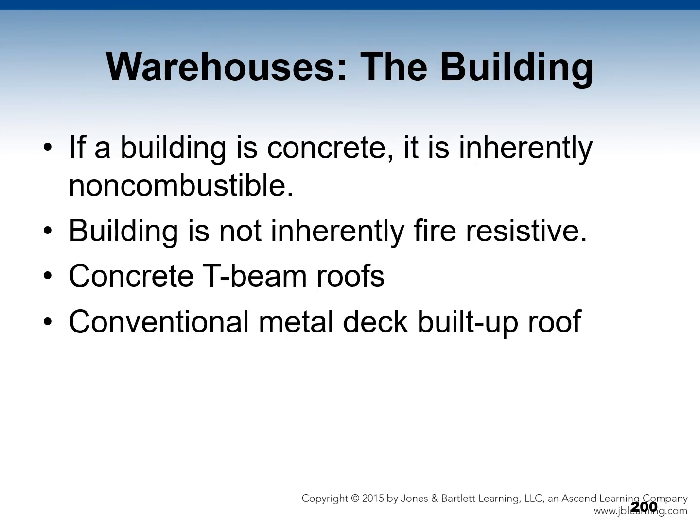Let's talk about warehouse buildings themselves. If a warehouse is concrete, it is inherently non-combustible. The building is not inherently fire-resistive. It can disintegrate or collapse, so make sure you bear that in mind. Concrete T-beam roofs are subject to spalling or disintegration of the concrete below the tendons. Conventional metal deck built-up roofs can burn independently of the original fire.